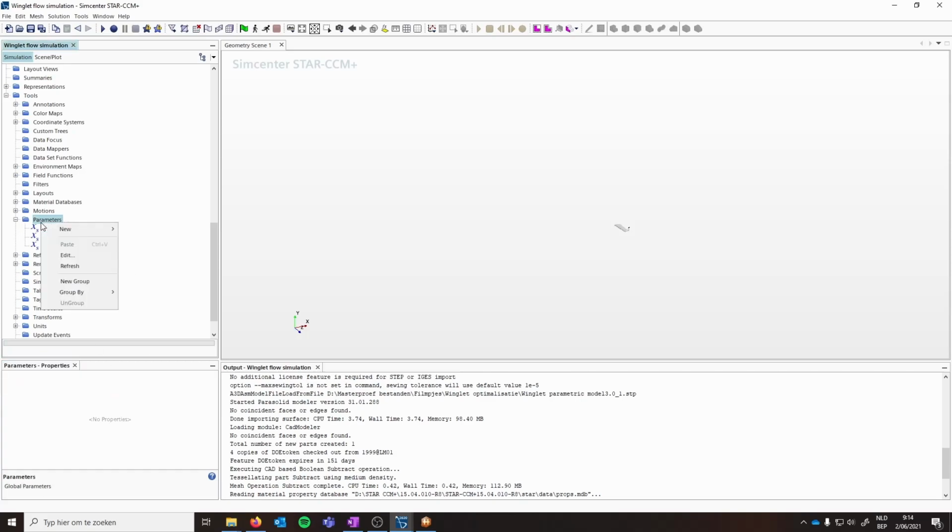Those are also variables that I will have to define. So this will be the angle of attack in degrees, and this will be the angle of attack in radians. So we'll start at an angle of attack of 0 degrees, and then to convert this into radians, we'll have to use that formula. So the angle of attack times 3.14, that's pi, divided by 180. So now the x velocity is defined. Now the y velocity has to be defined as well. And this has to be velocity.